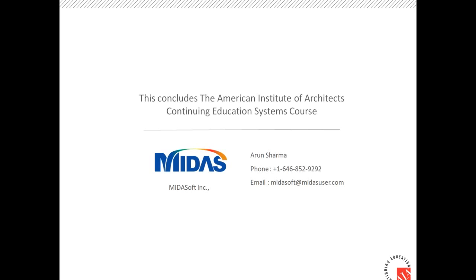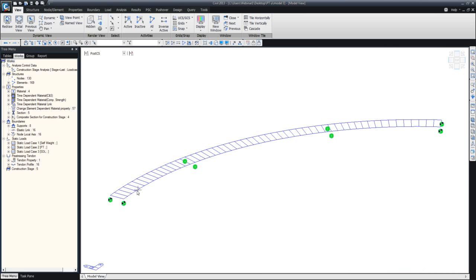So what we are doing here is modeling the cross section as a line element with all the stiffness taken in the longitudinal direction, and these dummy beams are the members that are connecting the adjacent girders together to transfer the forces from one member to another.